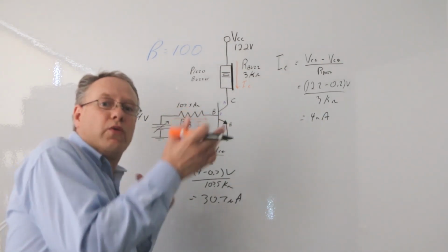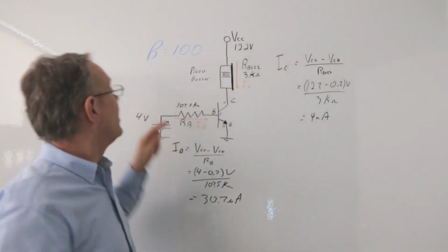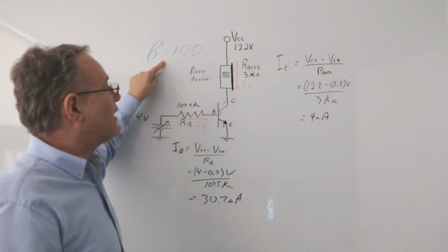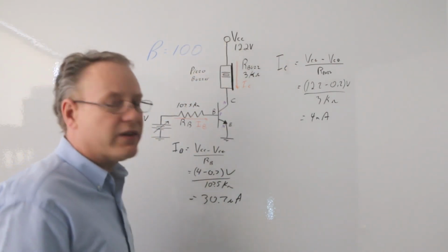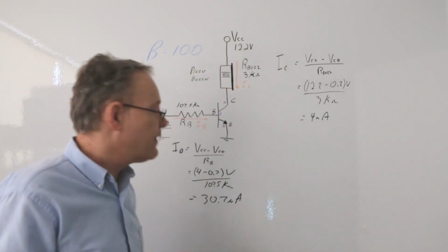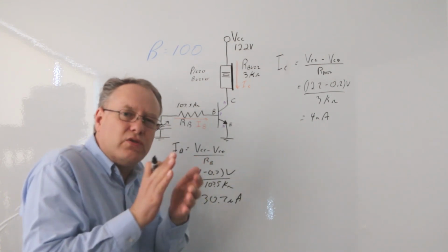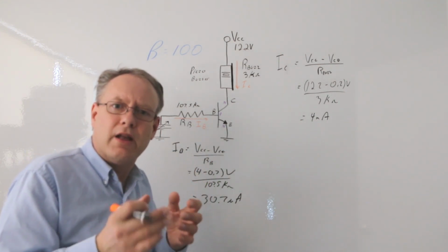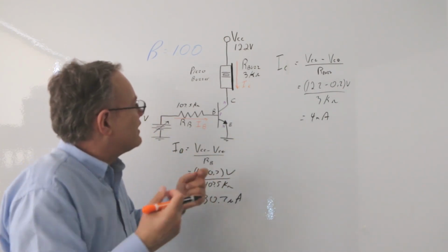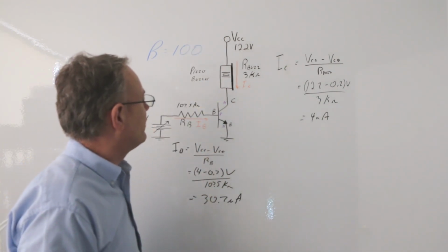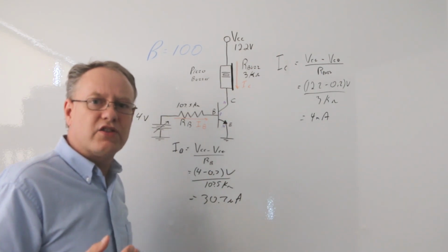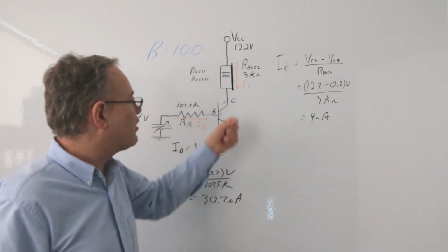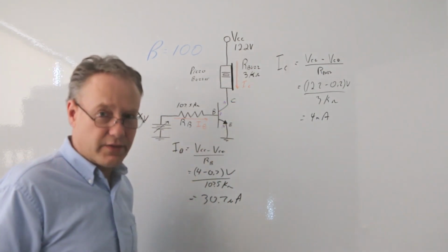Let's look forward. Let's look through the transistor using my gain to find out how much current is actually going through here now. Has it changed? Actually, it has, because this guy is closed a little bit. It's no longer fully closed. It's actually opened a little bit, so the switch itself isn't allowing the full current to go through. And we're going to see that there's a voltage drop across CE that's greater than 0.2.